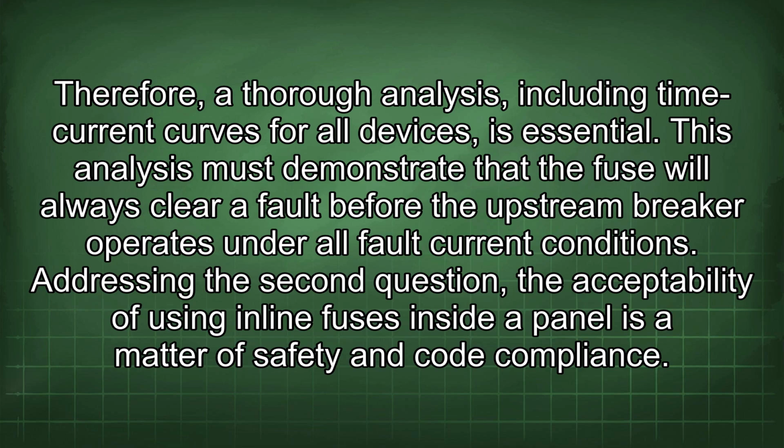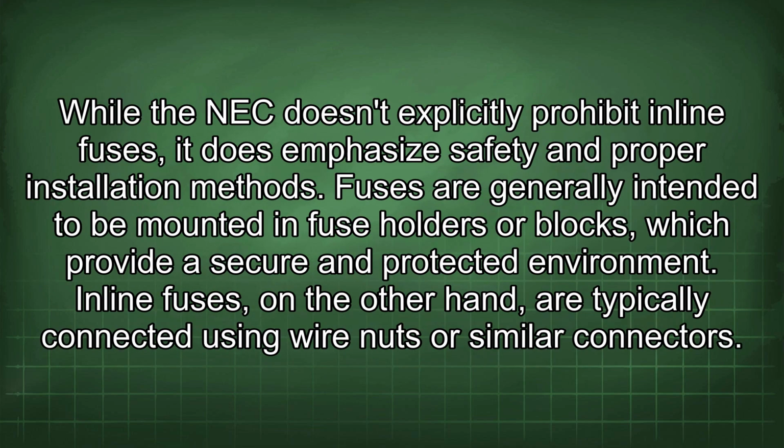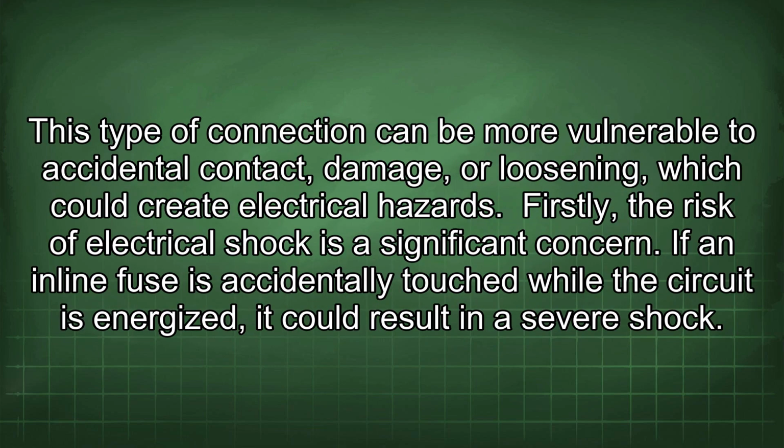current conditions. Addressing the second question, the acceptability of using inline fuses inside a panel is a matter of safety and code compliance. While the NEC doesn't explicitly prohibit inline fuses, it does emphasize safety and proper installation methods. Fuses are generally intended to be mounted in fuse holders or blocks, which provide a secure and protected environment. Inline fuses, on the other hand, are typically connected using wire nuts or similar connectors. This type of connection can be more vulnerable to accidental contact damage or loosening, which could create electrical hazards.